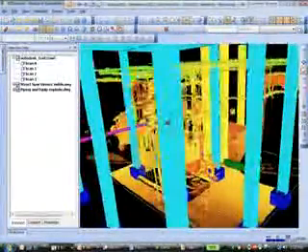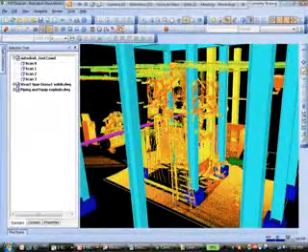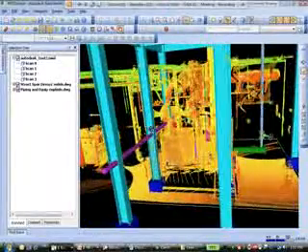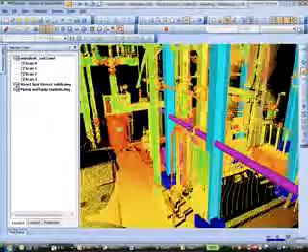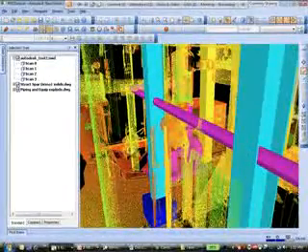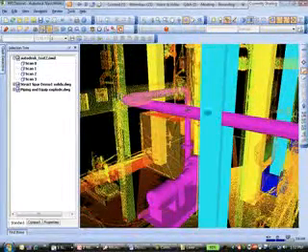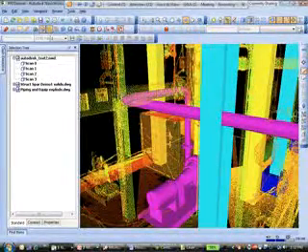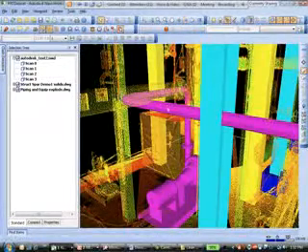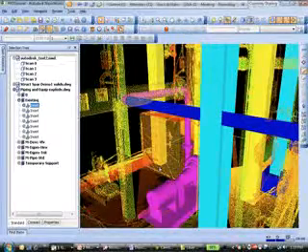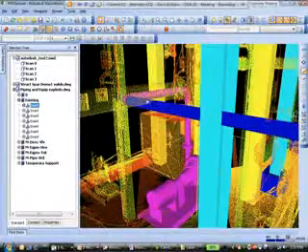Yeah, exactly. So Navisworks is not a design tool. It's really more of a tool to help you visualize, analyze, and simulate different conditions. So in this case, when I ran the clash, let me see if I can find it. It was on one of these pipes. Here it is. It's over here in the corner. This pipe that's coming along here, you can see it's interfering with that. I would go back into the design application and probably take this particular pipe here and move this down, just so that it's clearing this issue, where it's interfering there.